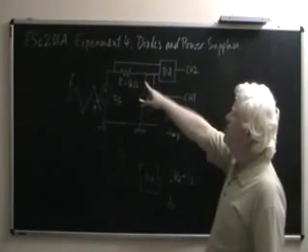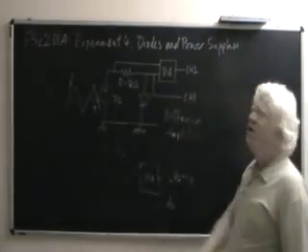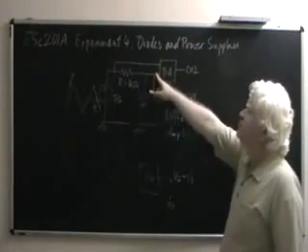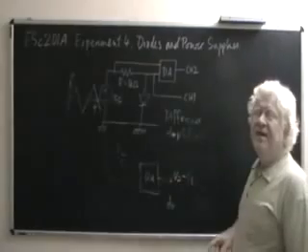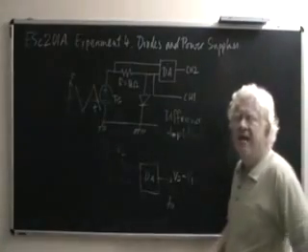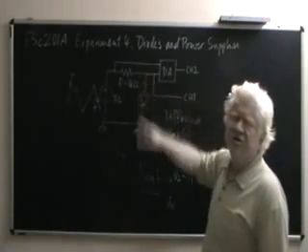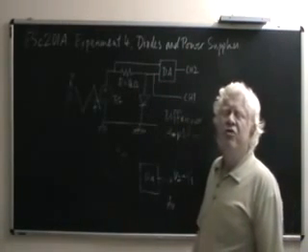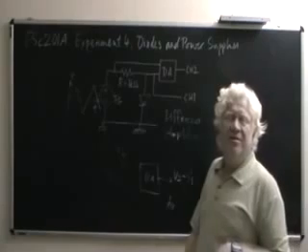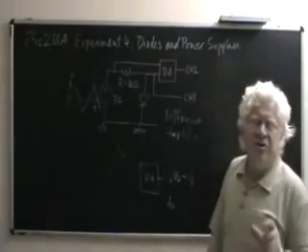So, the floating voltage across the resistor is converted by the difference amplifier into a grounded voltage, which goes to channel 2. The diode voltage here goes to channel 1. There is in fact a means of measuring a floating voltage even with an oscilloscope, and the right way to do that would be to connect this to one channel of the oscilloscope and this to the second channel of the oscilloscope, and then use arithmetic features of the oscilloscope to subtract channel 2 from channel 1 and plot that waveform, which is the subtraction of these two quantities, of these two functions.